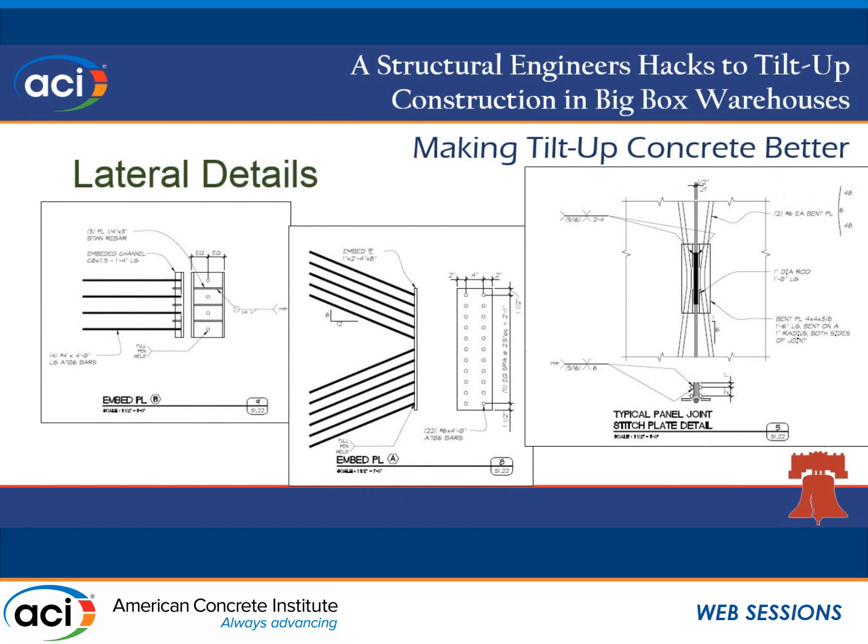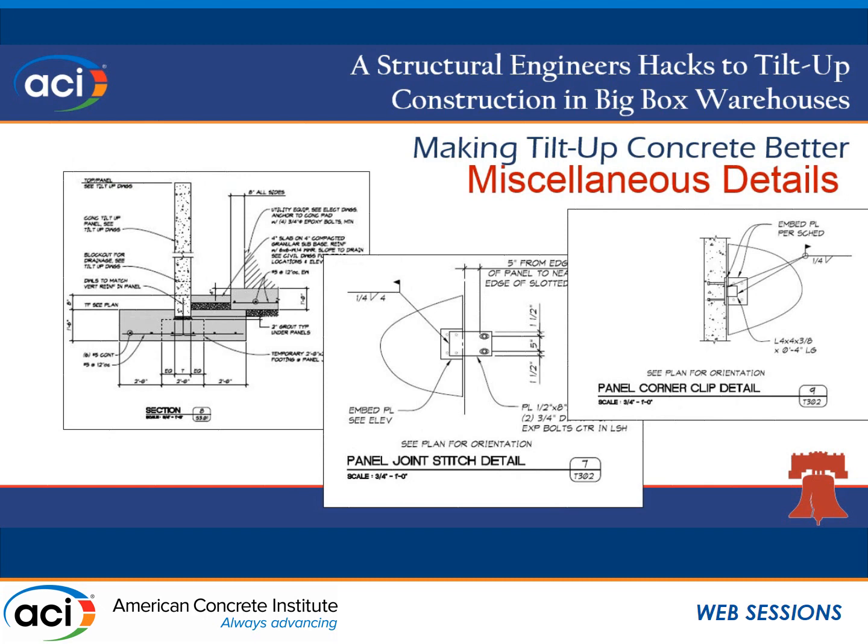I stole that one from the precasters, but wherever you can use a rod, it's going to cut down on the cracking. I know you guys don't like it, but I tell you, the thinner the piece of steel is, the less heat shrinkage you're going to get and the less cracking you're going to get. But they suck. They really do. There's just too much rebar there to deal with.